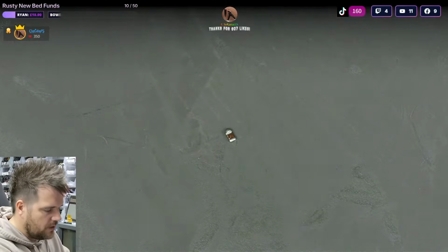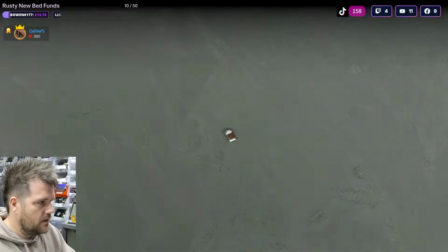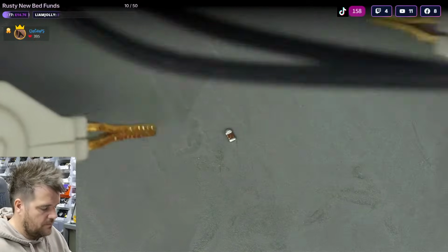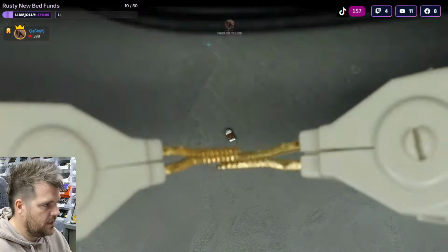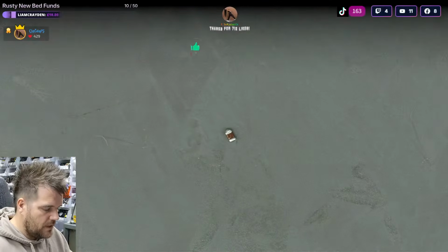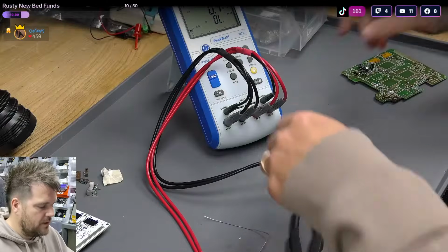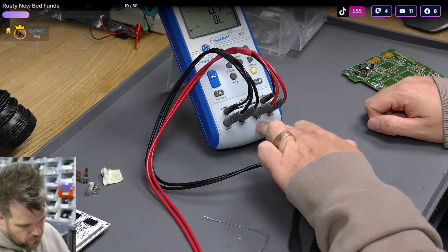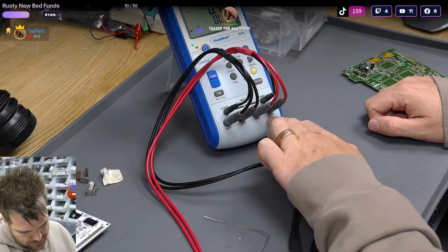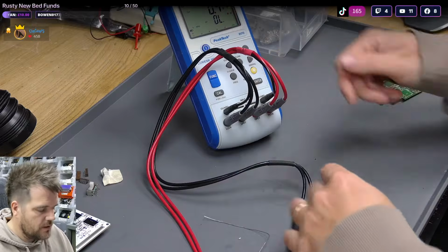Now the goal is, with the LCR meter, you've got these big prongs. These have 2 pins each. I can remake it so I can just grip on, and it's accurate enough. But technically, because these are proper, they have 2 pins. One is for the H pot and H current, so you've got a potential and a current pin going in, and a guard.